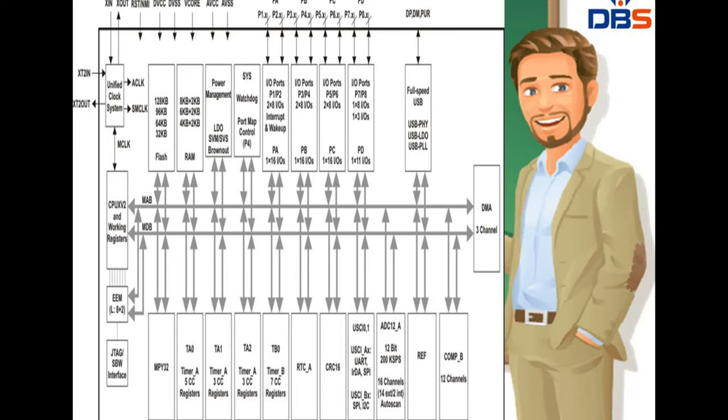The timeout signal is used to initiate corrective actions like placing the system into a safe mode or restoring its normal operation, so that it will be refreshed or restarted again. The watchdog timer is also used to generate timely interrupts for an application. Suppose you need any timely refreshing, it is going to generate it automatically.